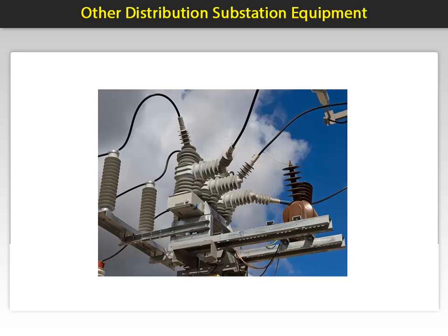These could be because of cables momentarily touching, a short lightning strike, or surges causing a spark. If the fault condition is still present after 3 attempts, the recloser is programmed to consider the problem permanent and it remains off. These could be the result of a lightning strike, fallen tree branches, or motor vehicle crashes. A power company crew must then repair the problem on the line and reset the recloser to restore power. These are available in single phase, providing independent protection on each phase, or 3-phase protection.